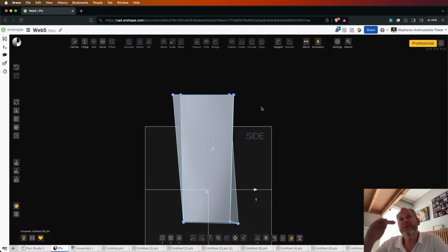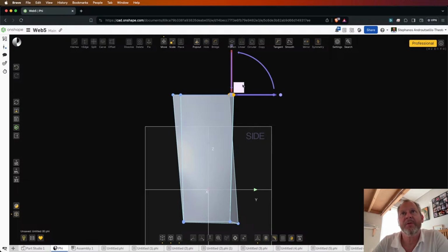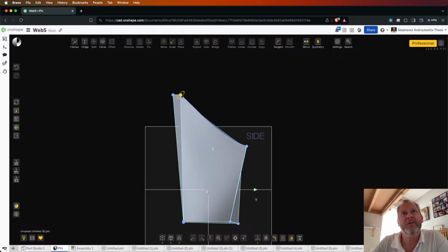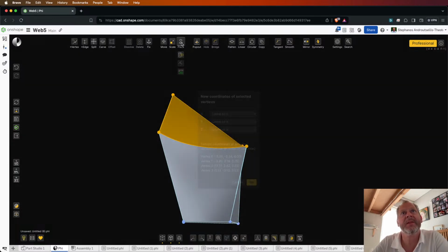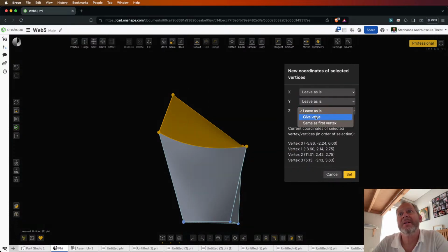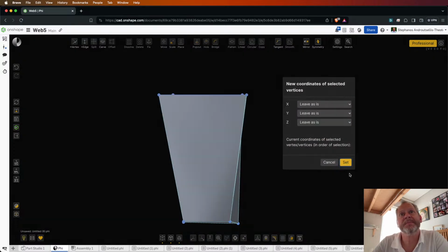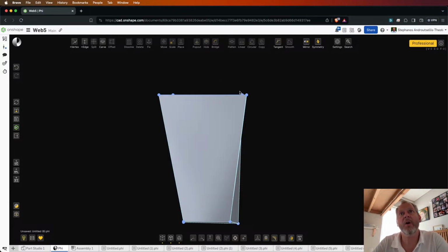so that now, if I switch in this view, all of the vertices moved so that the z coordinate of all of them became the same as the z coordinate of the first vertex. So if I, for example, move these 2 guys down here, and I move this guy here, and I repeat it once again, because again I'm not very happy with the viewpoint I had selected. And I make z the same as the first vertex. Okay, I think now it was obvious. All of these vertices moved up in the same plane that cuts the z-axis where the first selected vertex was.